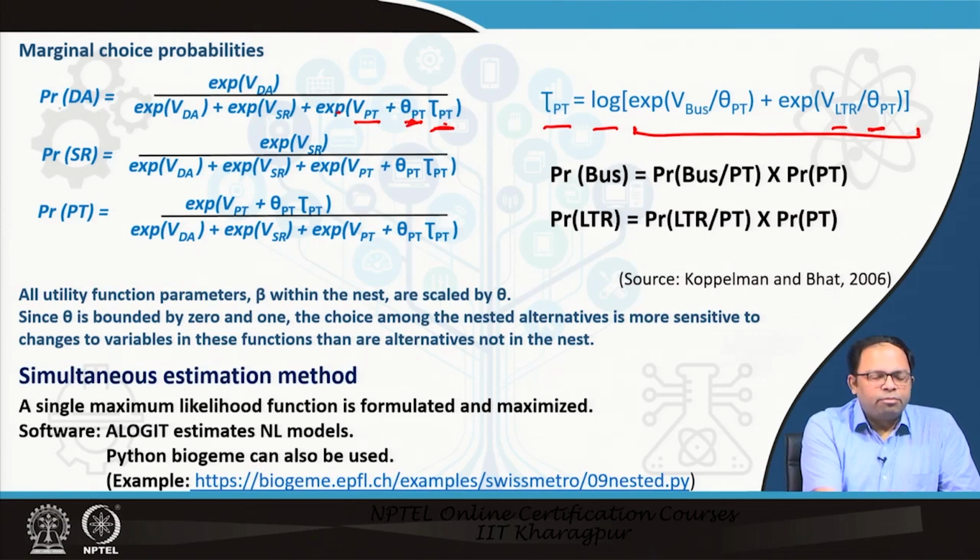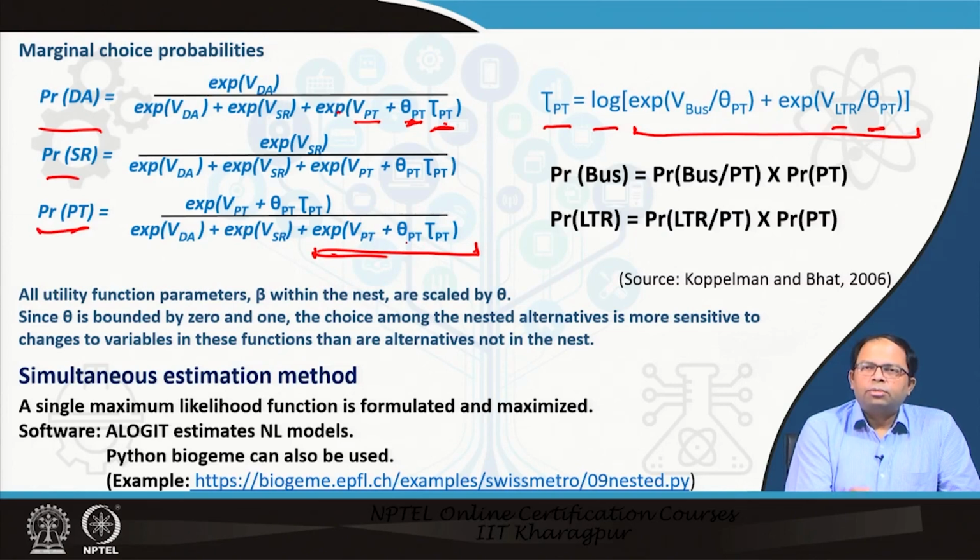So, if I write my probability equations in this particular form, with V shared ride, we are also determining the composite transit probability in the same way. So, we are bringing this form over here, which is the composite utility of transit, which we have learned is composed of the log sum parameter times the log sum variable plus the characteristics of transit. So, that is what is given over here.